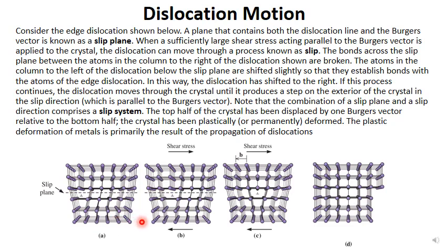The most acceptable and energetically favored scenario is that something has to happen around the dislocation, because having a dislocation in the crystal structure introduces a distortion to the structure. This region here has more energy than others, and anything that would occur would start from here.